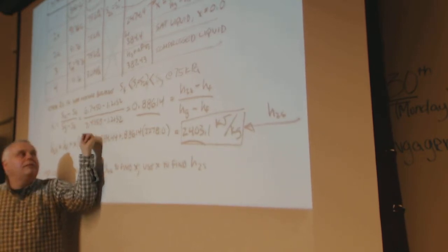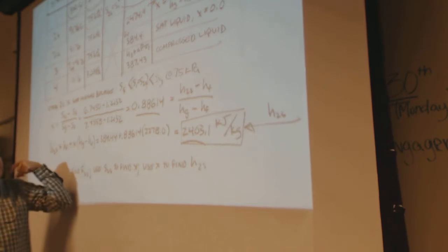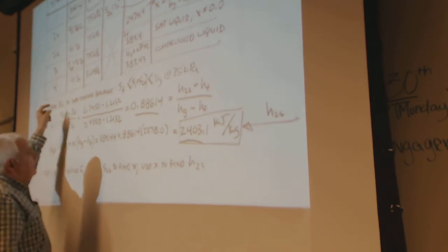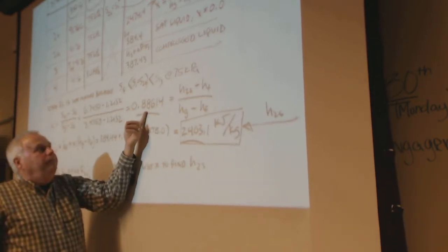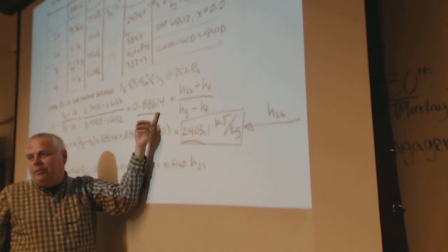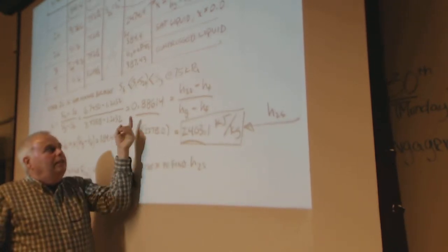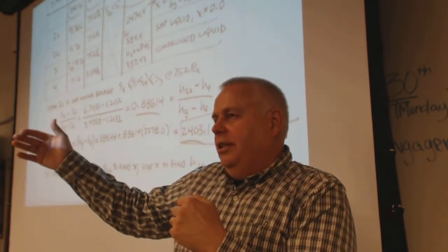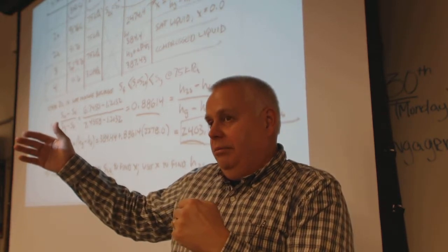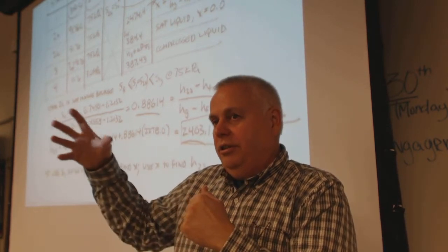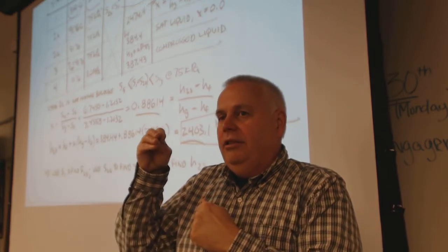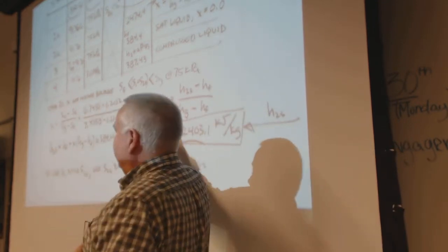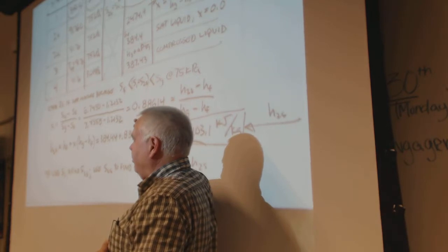It's a fog. How thick is the fog? So we do this to find how thick the fog is. It turns out to be 88.6%, or 0.886. It's 88.6% of the way from being liquid to being completely saturated vapor. Saturated vapor, like steam, is clear. You don't see it. It's when it starts condensing, the droplets that are actually liquid suspended in air, that's the fog that you see. So what would you call that? Like 11% fog or something.